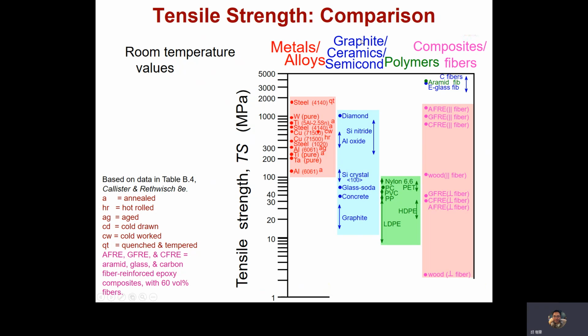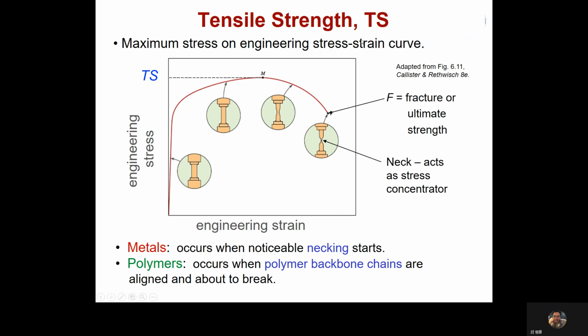Okay, so let's look at the stress and strain curve from the tensile test. We can figure out several material properties or mechanical properties of metals from the stress and strain curve. The first one, which we already mentioned, is the slope of the stress and strain curve within the elastic region, the E. And the ultimate tensile stress, UTS.